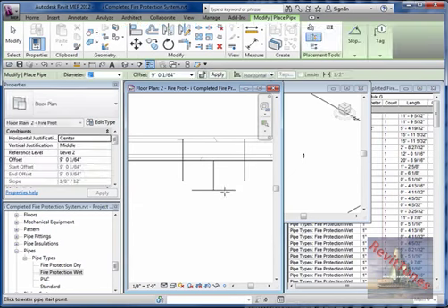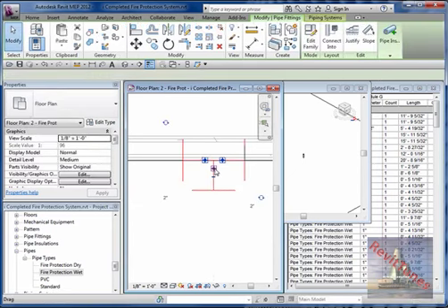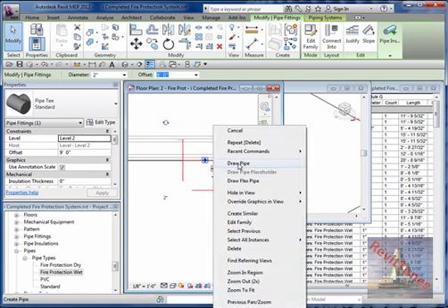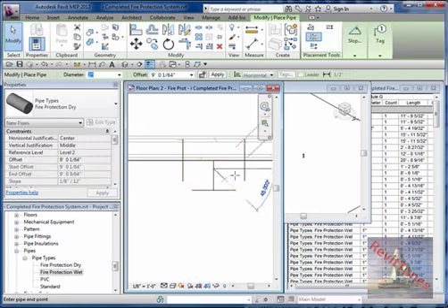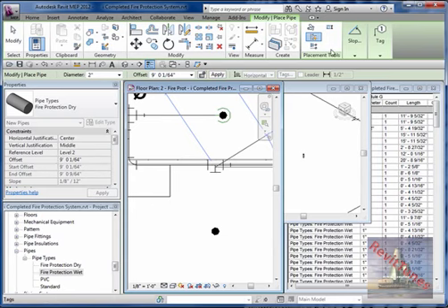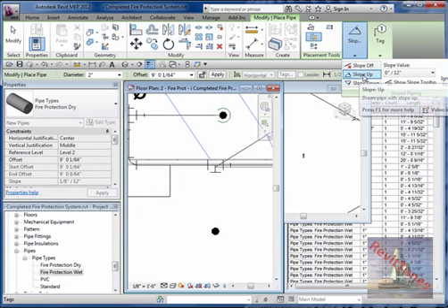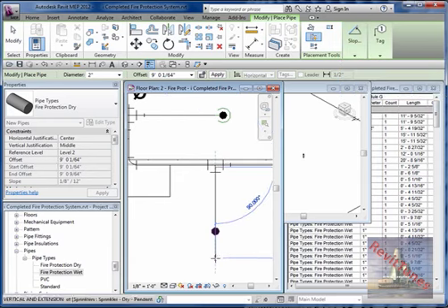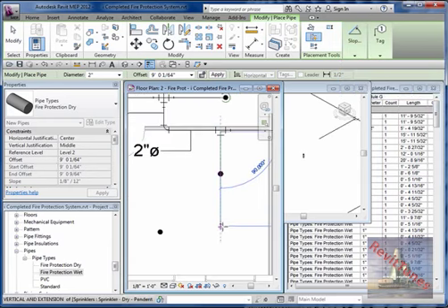I forgot one thing. I'm gonna do it again. I forgot to hit the space bar. So the space bar will grab the appropriate height. Draw a pipe, now hit space, so it grabs the height of this pipe. And now the slope, let's see if it's still... we lost the slope, 1/8 of an inch up. Okay, so I hit the space one time.